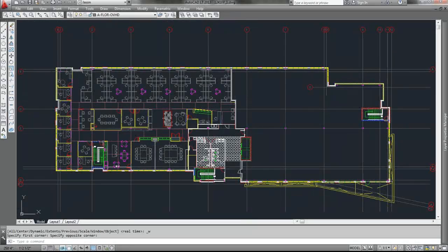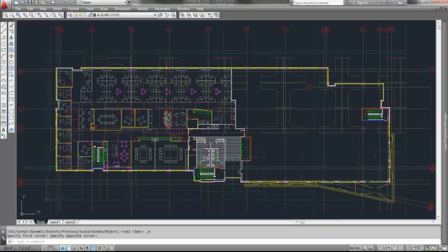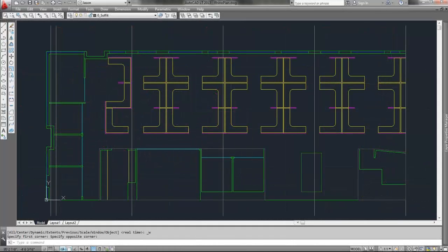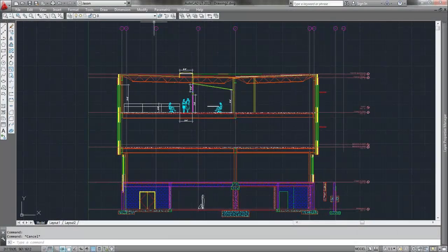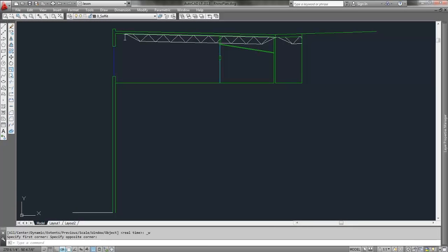Often the project documentation provided by the owner or architect contains more information than needed for the daylight model. The first step, therefore, is to refine their documents to create purpose plans and sections in a CAD package. Important things to include are space and glazing areas, as well as thickness and dimensions. Furniture and other large interior structural elements are also important to include. However, the more elements you add, the longer the daylight model will take to calculate. So it is important to include only those elements which will significantly influence light levels.